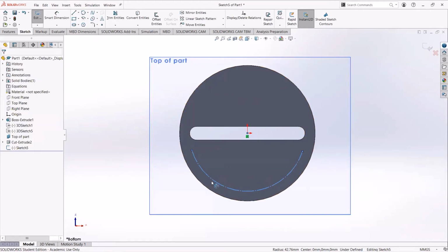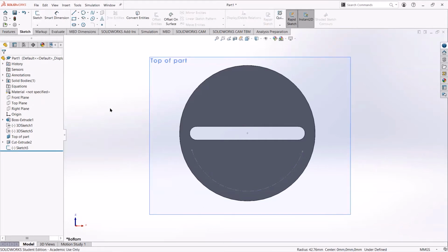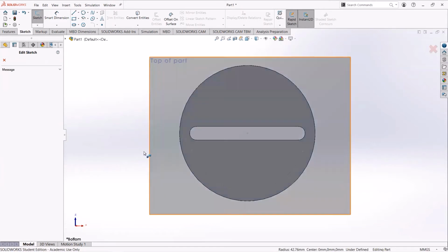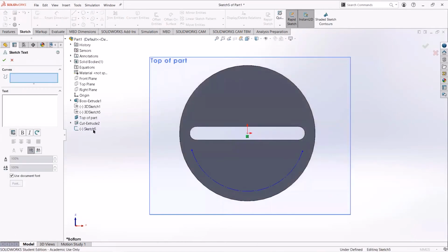And I'm gonna say that we didn't start out by clicking that sketch, right? So I'm gonna click escape a bunch of times, and then I'm gonna exit the sketch. If you click escape a bunch of times after that, nothing really should be highlighted. And then if you tried to click on this text, it'll say what I mentioned earlier, where you have to navigate through this little button right here, this one right here, and then you have to go to the exact sketch that you wanted.